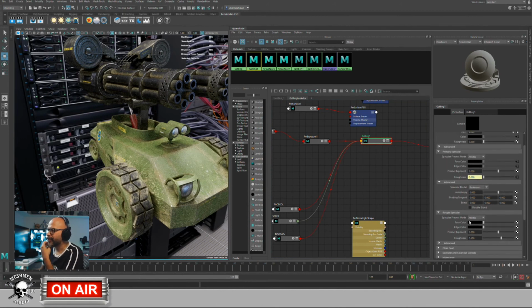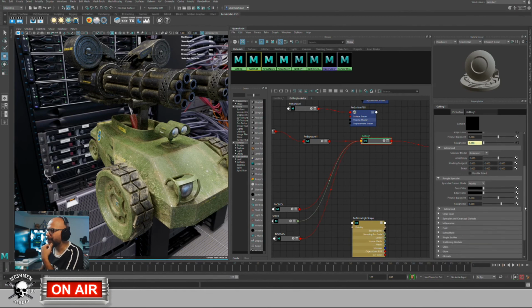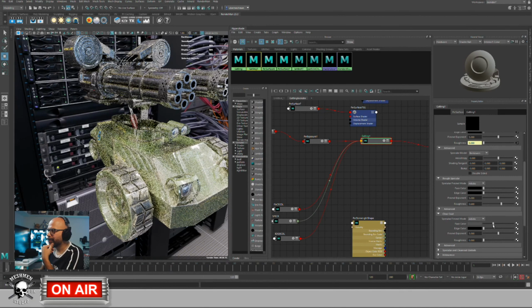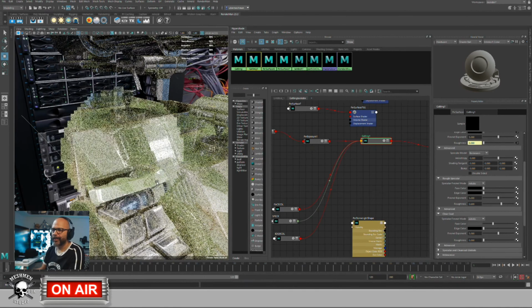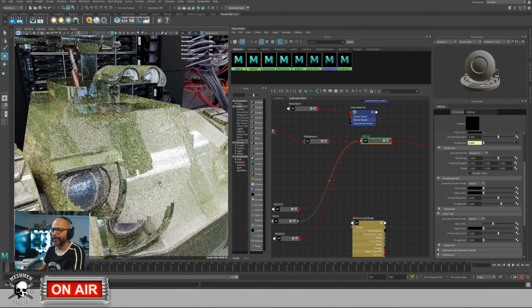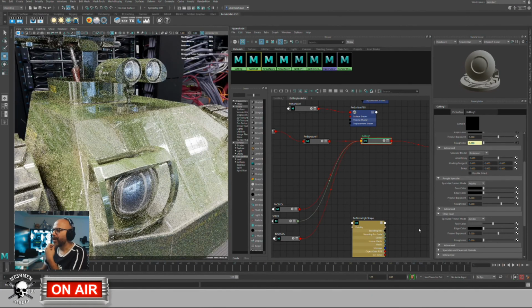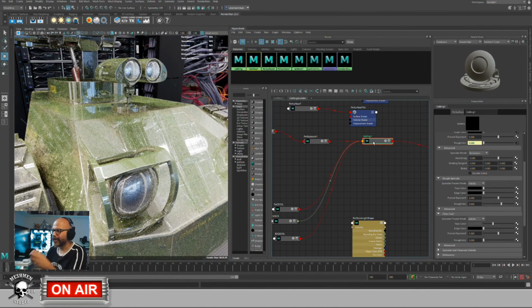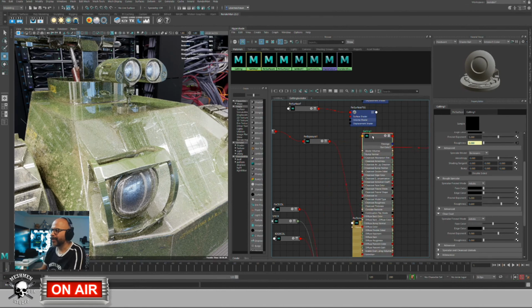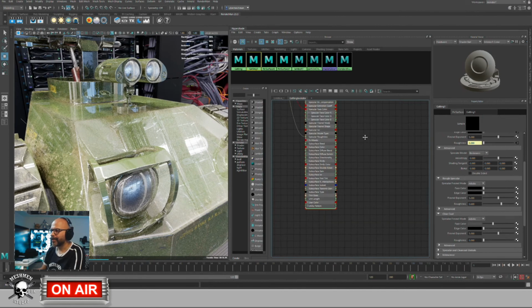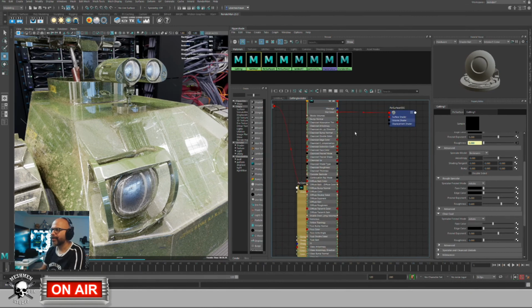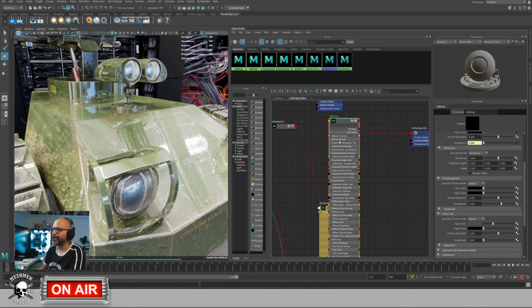Okay, so let's actually do that by using a clear coat. Just gonna take a bit of clear coat like I have a lacquer on top of everything here. So we can see here, you can bump individual lobes or everything. So in your shader, let's take a look down here at the bottom, I believe it is. Is it at the top? Bump normal. If I plug anything into bump normal here, it's gonna bump all the lobes.